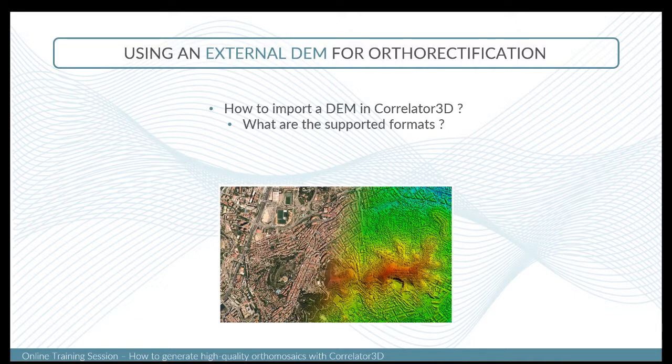If you have LiDAR in LAS format, you can bring them in the software. However, you will first have to convert your point cloud into a regular raster DEM in GeoTIFF or ASCII grid before importing in the software.